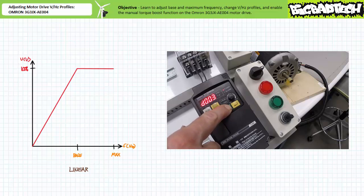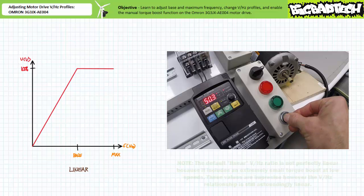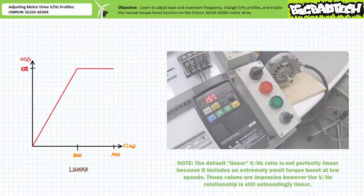When we return to display parameter D001, the output frequency monitor, we can readjust it to provide a 48 Hz excitation frequency, or 80% of the base frequency of 60 Hz. When speed stabilizes, we can navigate back to parameter D013, output voltage monitor, and find the motor drive is applying roughly 80% of the available line-to-line voltage. As we'd expect, applied voltage as a function of frequency appears to be linear, only this time, excitation frequency is limited inside the range 0 to 60 Hz.